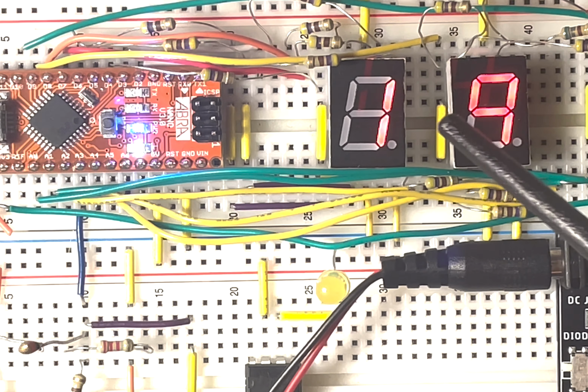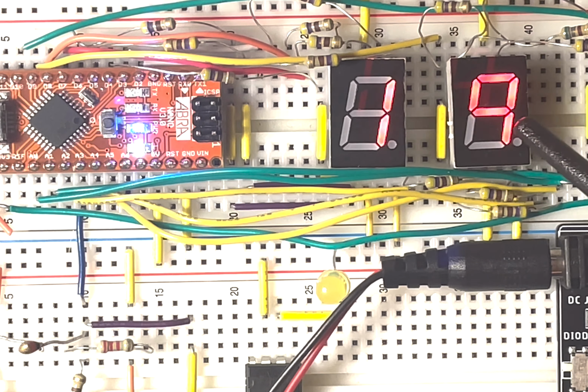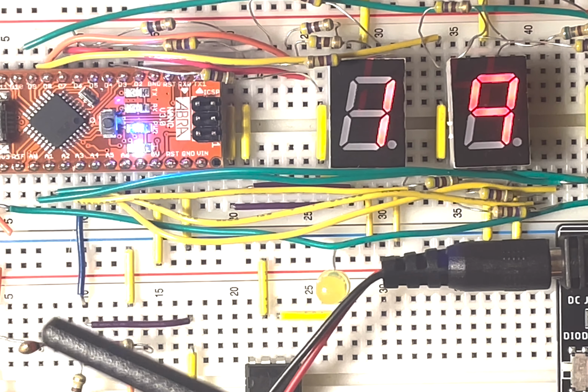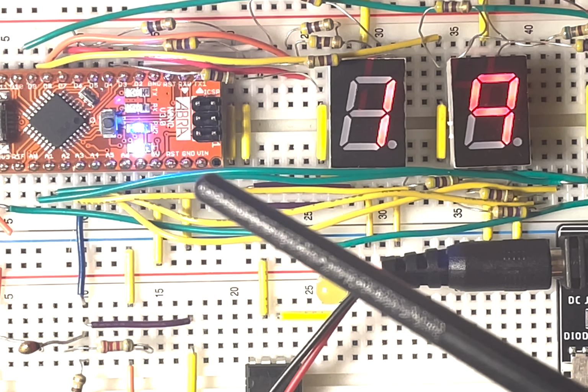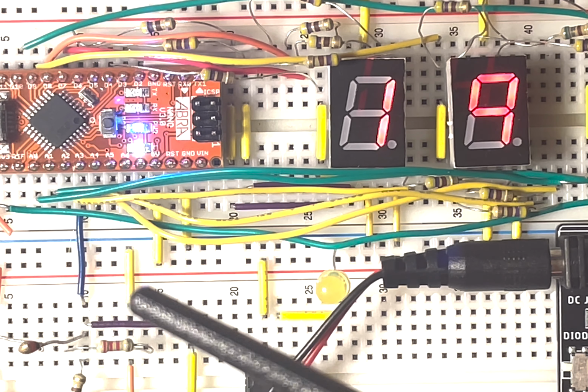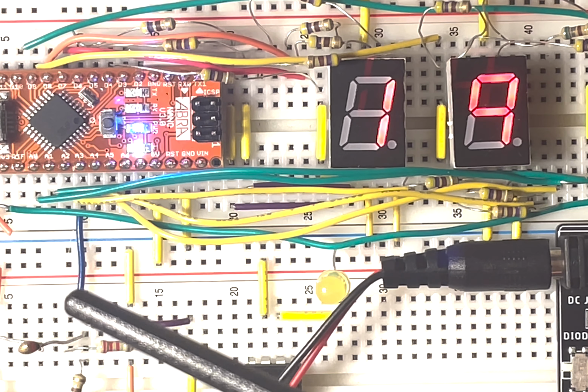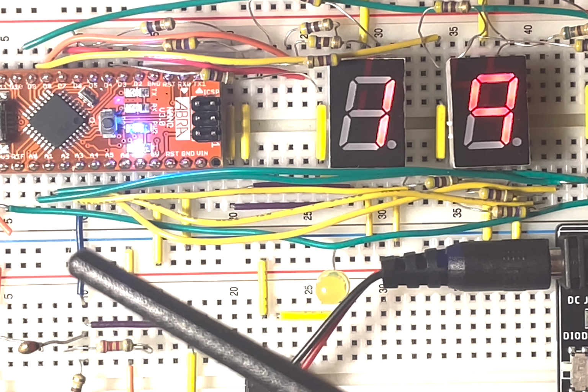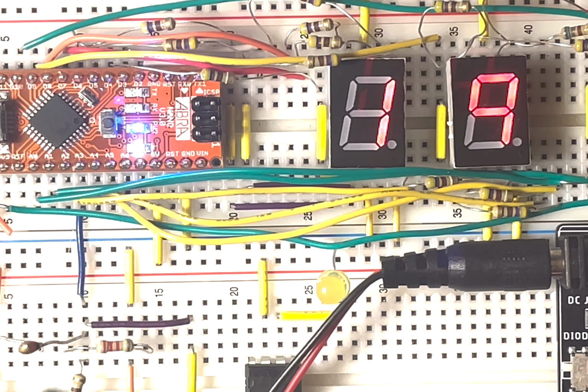Now you may notice that this temperature will not be entirely accurate. And this is because of one simple reason: the Steinhart coefficients. Every Steinhart coefficient is different for every thermistor, because the thermistor's change in resistance based off of temperature is a nonlinear relationship. It is exponential. Whenever you use a new thermistor, you need to find the new Steinhart coefficients. This would involve exactly calibrating the thermistor with exact temperatures and exact resistances.